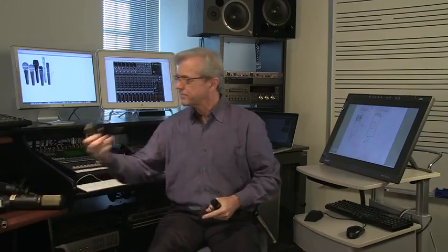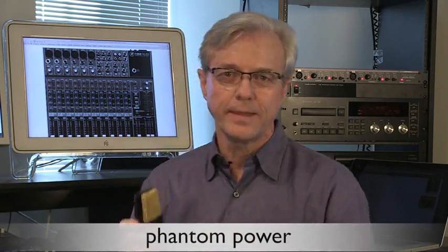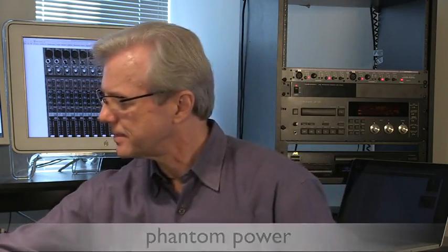Here is another condenser microphone. This is an AKG C414, which is a very classic microphone. This does not have a power source on it. So when we plug the microphone cable into this, which we'll get to cables in just a second, the microphone cable has to go somewhere where the charge can actually be sent into the cable. That's called phantom power. Phantom power was first developed by really the German microphone company called Neumann back in 1966.